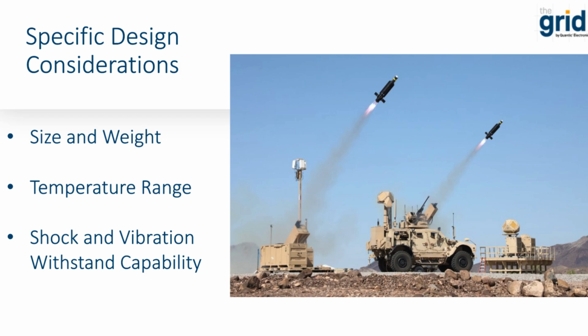Some capacitors work exceptionally well in lab environments, but several ruggedized alternatives provide the needed electrical performance for use in harsh environments. Now, there are several MIL standards that specify shock and vibration tests designed to simulate the most aggressive field conditions, which capacitors are often designed to pass.